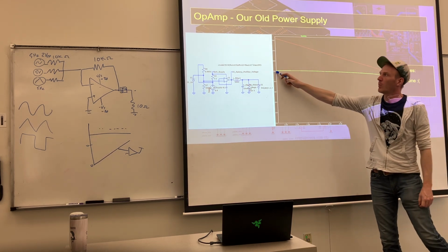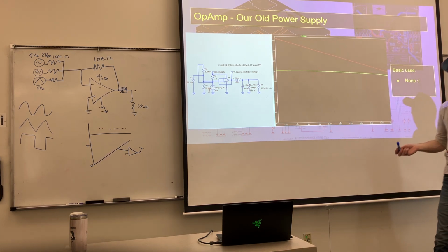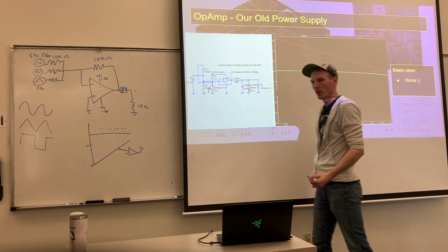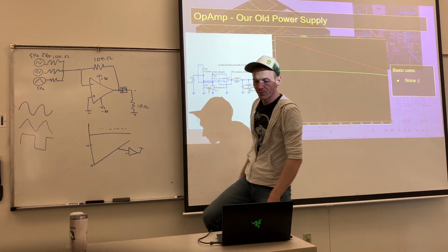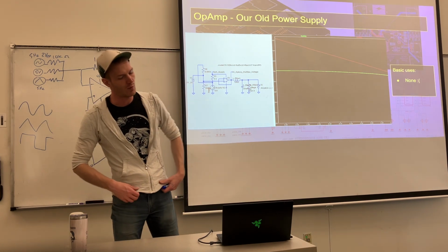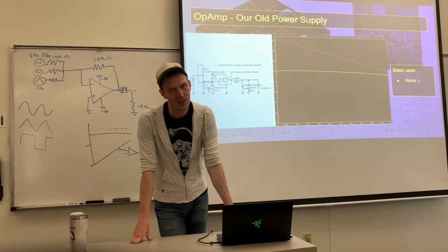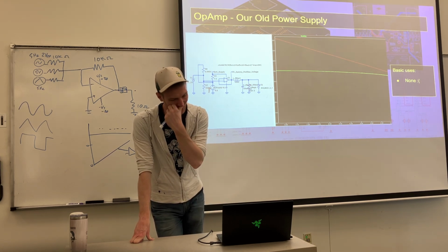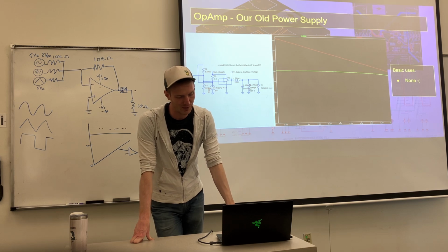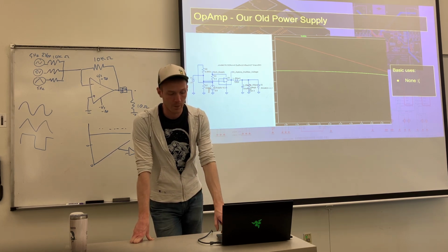And we see that our output voltage is pretty stable around 5 volts the whole way across, which is exactly what we're kind of looking for. It has a very small droop, which is more of a load sharing characteristic term, but it still kind of applies here. So there's a slight droop. In reality, we got exactly 5 volts, so it might be one of those cases where the real case was a little bit better than ideal. Any questions before we move on?